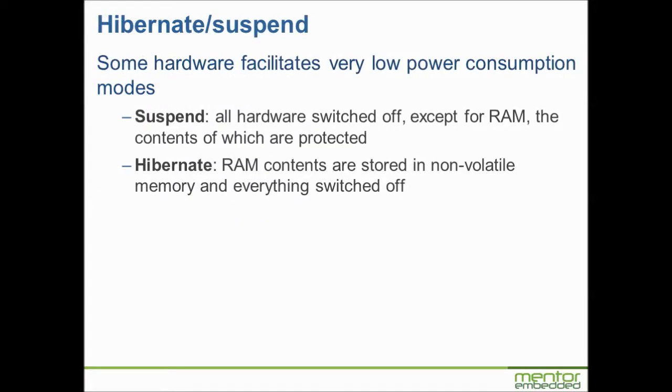So typically, there are two low power modes which correspond to suspend and hibernate on a PC. In fact, we tend to use the same names so that we know what we're talking about. In suspend mode, all the hardware is switched off except for the memory, and that is retained at the lowest possible power level in self-refresh mode so that the data in there is protected. In hibernate mode, absolutely everything is switched off, but only once the content of data has been written to some non-volatile memory. Now, on your PC, that's written out to disk, but obviously on an embedded system, you're unlikely to have a disk available. It's more liable to be written to flash memory or something of that ilk.